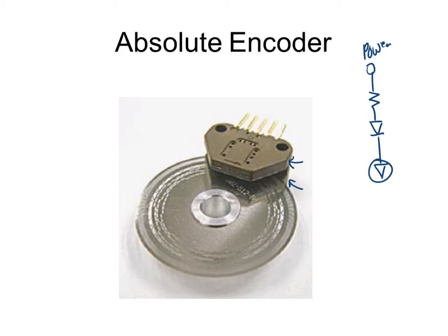We would have to have power right here, and then we would have to have a common. Well, that's 2 pins right there. You can't say it's 5 channels when 2 of them we have to have for power. We can't see down below if there are more pins. There might be another set coming out down here that we can't see. So I don't know what channel it is. There might be electronics in there that takes in the head where we power it up, and it might take 15 LEDs and convert them over to a serial representation of that. Understand? So this guy right here could actually be an electronic device.